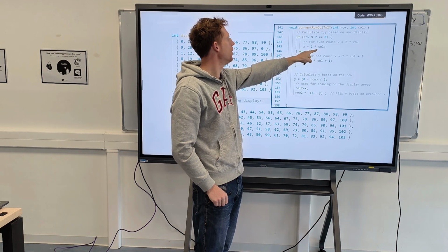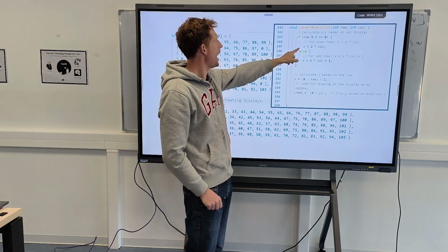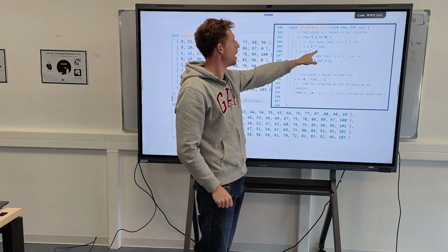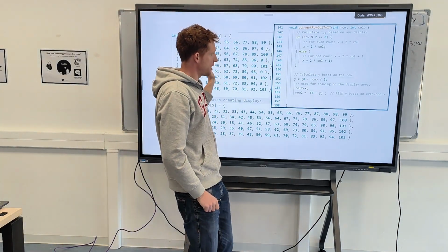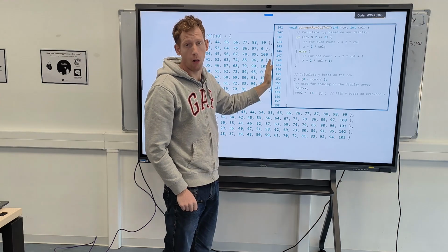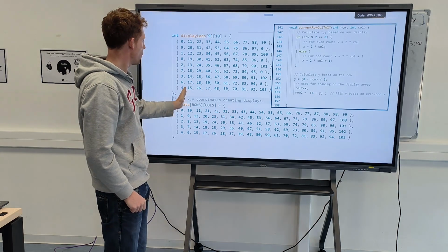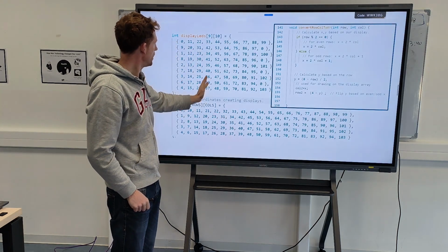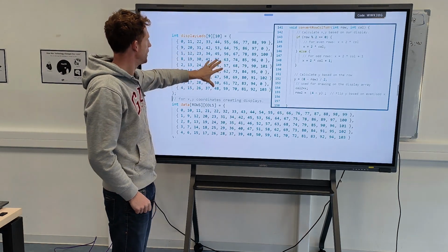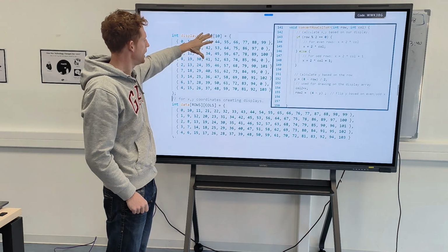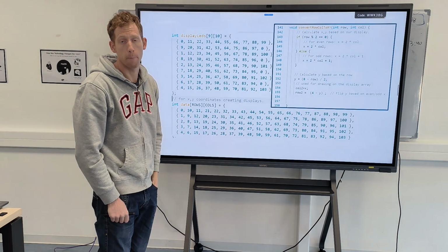If it's 0, then it's an even row, okay? And so your X is going to be equal to 2 times the column number. And then to figure out the other one, if it's false, it's going to be the column plus 1. And then that will go through right here. You're still going to get the rows and columns, but I don't need to use this previous LED display for the buttons to figure out what LED corresponded to what button pressed.